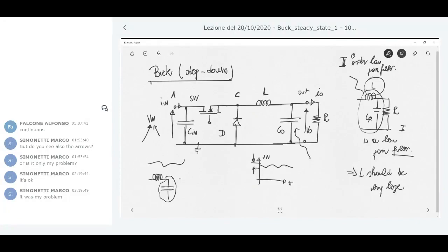Of course, the discussion can be formulated in detail later. Just to point out some specific considerations: the buck can be done simply with the switch, the diode, and the inductor, without CIN and without C0. But in all practical circuits, CIN for filtering the EMC is always there at the input side, and C0 is always there for increasing the filtering action.